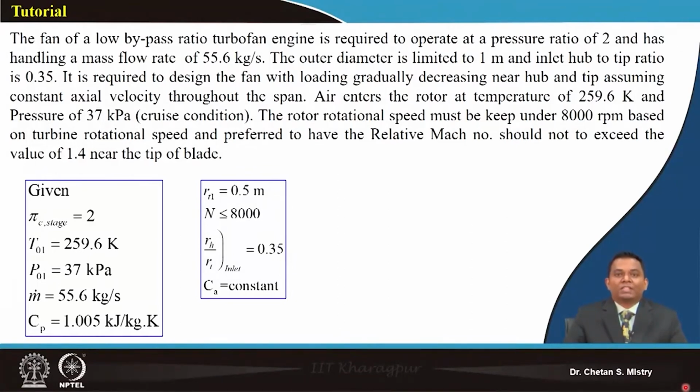So we must realize that by changing our wall distribution or load distribution, we are violating the law of radial equilibrium. As we have discussed many times earlier, especially for axial flow fan design, this violation has been valid, and people have done designs, and those fans are working absolutely fine even today, and that's what we are opting for here. So let's try to have a solution for this.